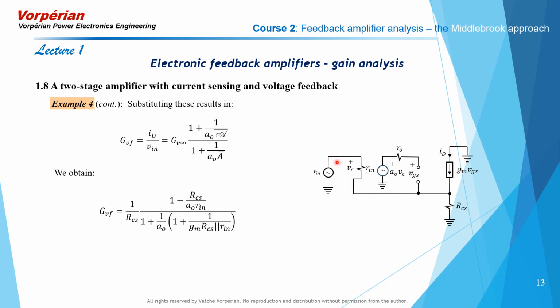The path through the amplifier, when the amplifier is functioning properly, is non-inverting, simply because if the input voltage increases, the current in this direction increases. It must be then that it is the path through the feedback connection that is the inverting path, and to see that, we just kill the gain of the amplifying path, and we determine what the gain is from the input signal to the output signal through the feedback path, while the amplifier is dead.